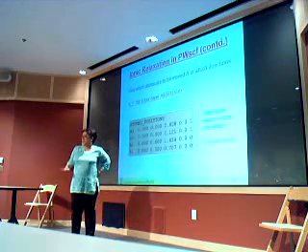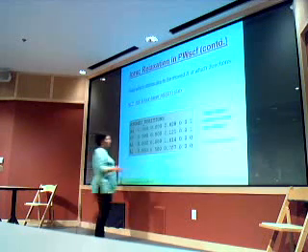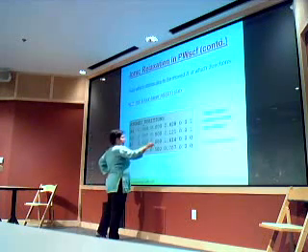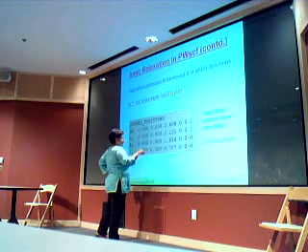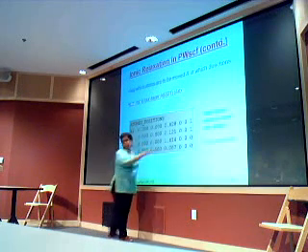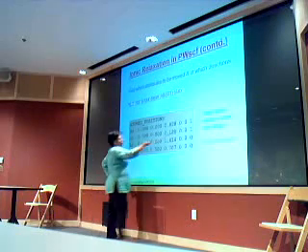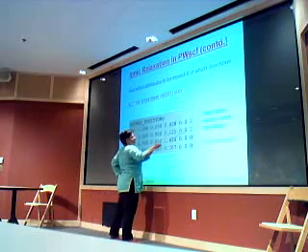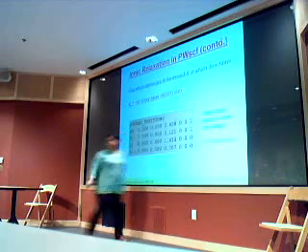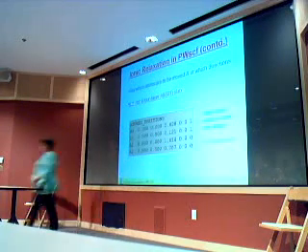And by symmetry, you know they're only going to move along the z direction. So therefore, for the last 2 atoms, after you put the coordinates, you put 0, 0, 0 to say that they shouldn't be allowed to move in any direction. And for these 2, you put 0, 0, 1 to say that they are allowed to move along the z direction.